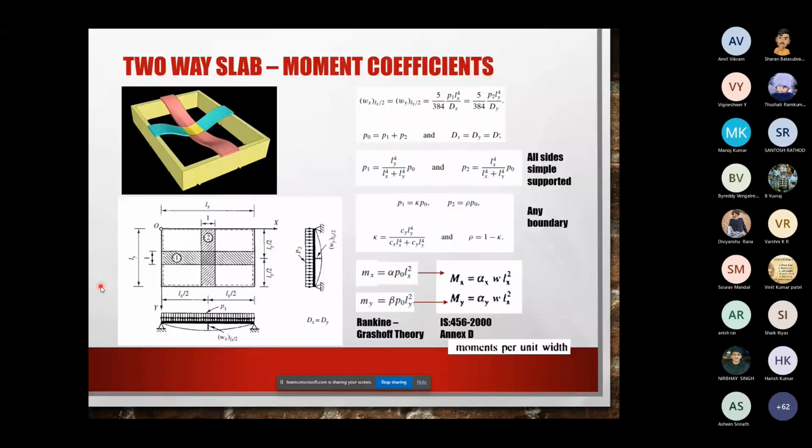Okay, the same spelling. You search Kirchhoff plate theory, you will see that there's a fourth order differential equation in x and y, a biharmonic equation. So solving that is not that easy, and unlike Euler-Bernoulli theorem, using that it's a headache for any general purpose. So therefore, nobody wants to do that. Nobody wants to solve such equations.